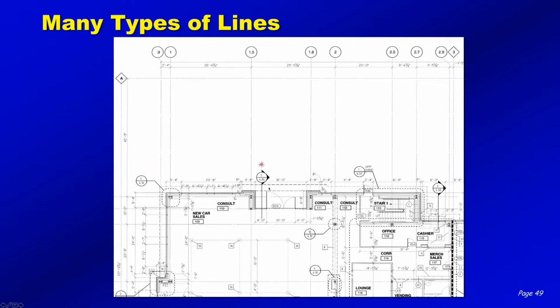Here you have a section mark. Instead of putting the arrow down here, you've got the arrow mark up there telling you to go look at detail 2 on sheet 6.06. And this is where you'll find the dimensions. Now, in this particular case, you see a little dashed line coming across here. And without giving a little bit of investigation, I'm not sure what that means. It could be something above, could be something below, but you'd have to go look at this little note right here that's got a little square that says go look at note number 8.